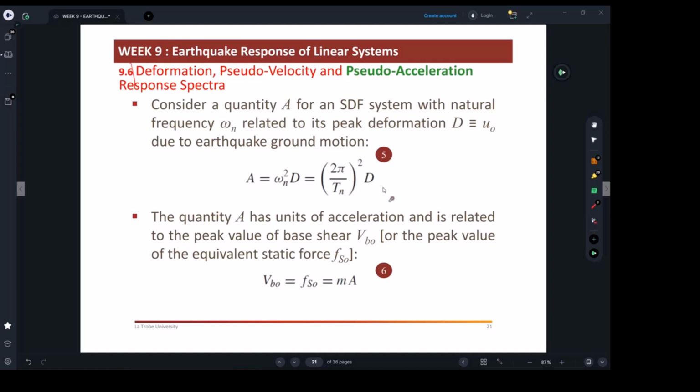And again, the other use of acceleration, which we all know about: if we have acceleration multiplied by mass, this will give us our shear force on the building, and then the shear force can be widely used to determine other stresses on the building.